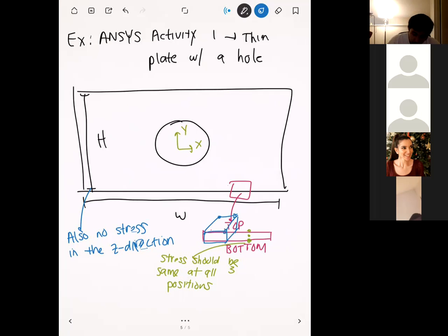We're kind of doing, you can almost think of it like twice the amount of work. Because if our plate has some thickness here, then we have 4 nodes on the top and 4 nodes on the bottom, right? But if we ran the simulation with quadrilaterals, we're only going to have 4 nodes per element, and so on a per element basis, we're running at half the cost, which is huge. Anytime you can knock off half the cost, that's a significant increase in performance.